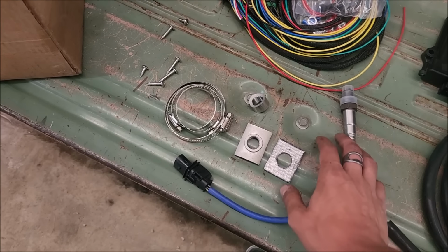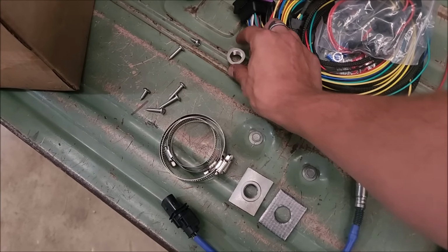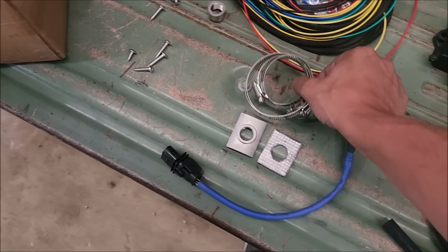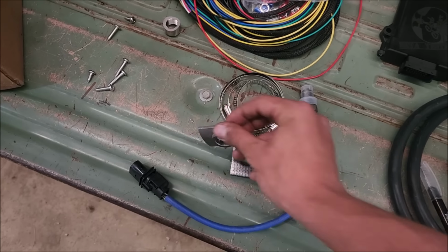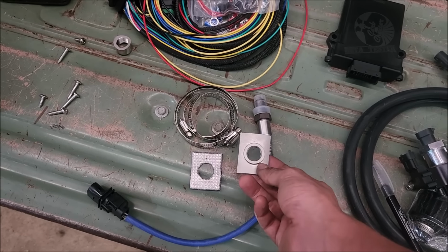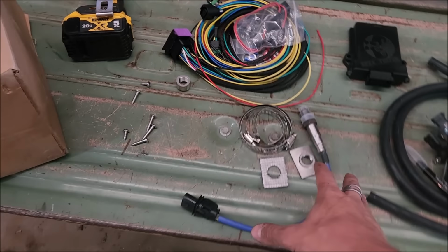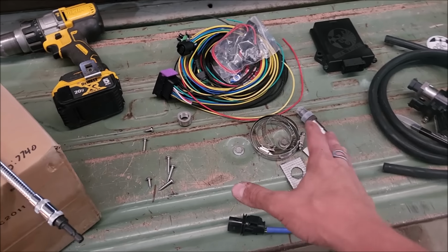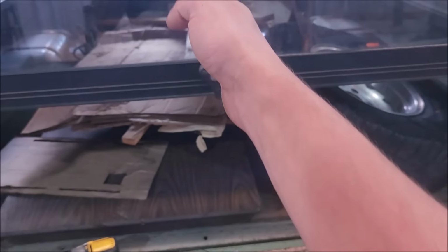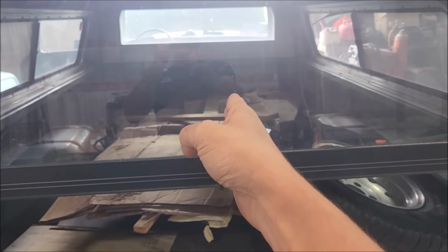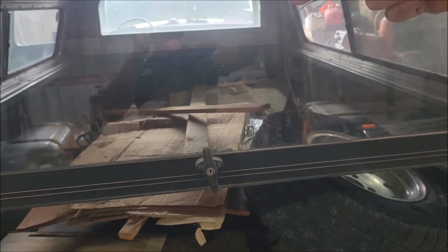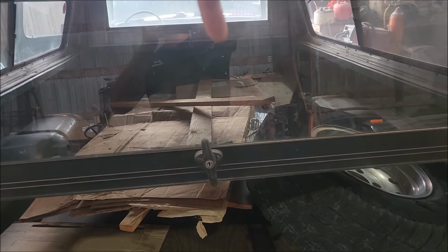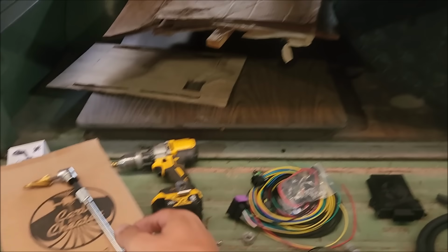Let's get it done. All right, our old friend, the wideband O2. So again, we're not going to use the weld-in bung. Got a couple of different size clamps for the different size exhaust and our stainless steel gasketed clamp-on piece. Now, installing this can be difficult, and if you're looking at an exhaust pipe running down your vehicle, you don't want to be side to side, and you definitely don't want to be pointing down. You want to come in from an upwards angle on the exhaust.